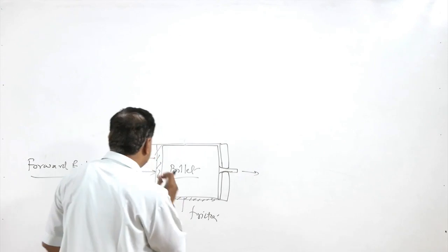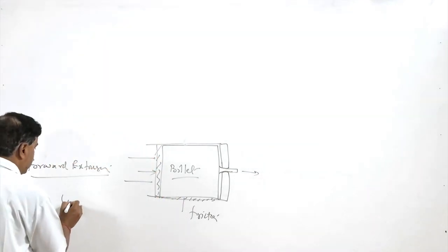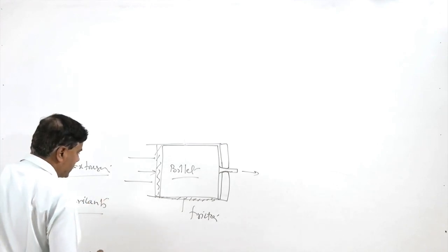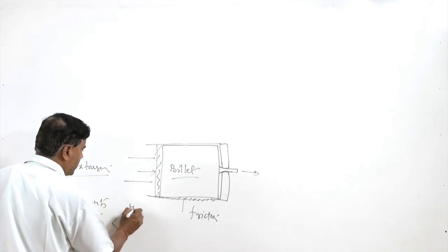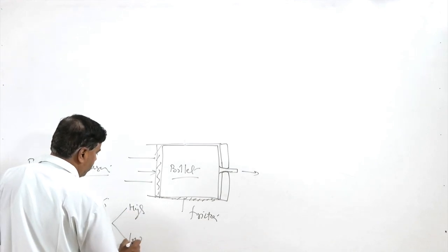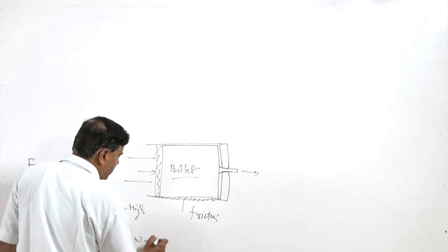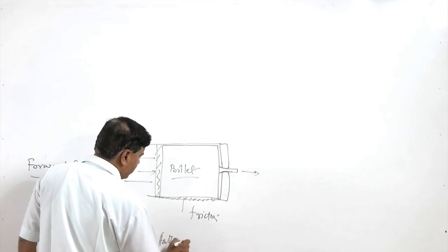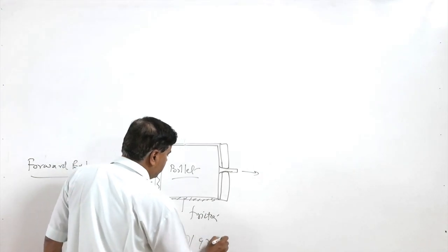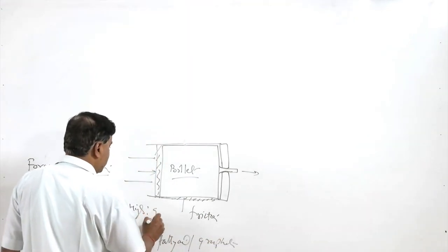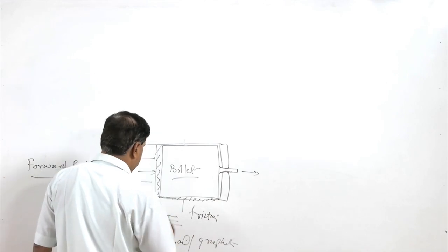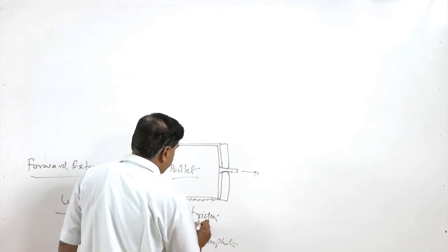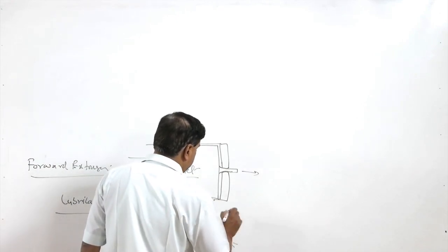To reduce this frictional effect, lubricants are normally used. Two types are used, one for high temperature and another for low temperature conditions. For low temperatures, fatty oils and graphite are used, while glass is used as a lubricant for high temperatures like 1200 degree centigrade for steel.